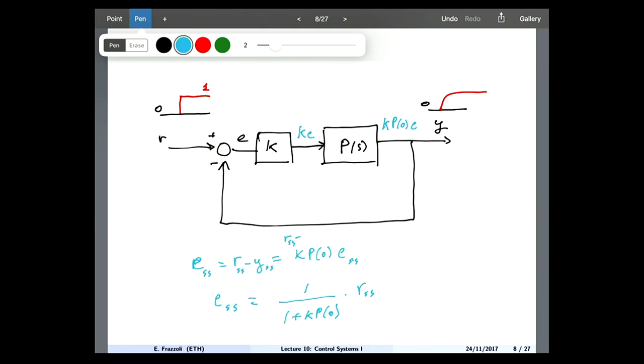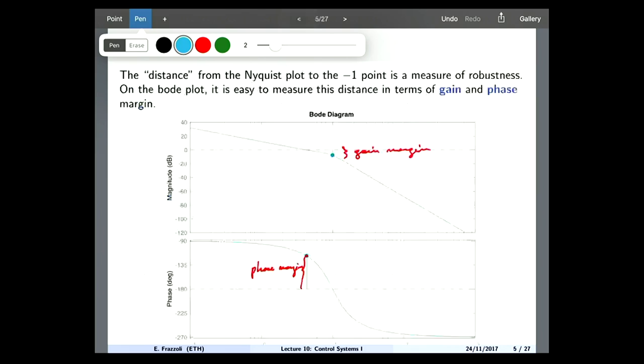So typically what happens is that by making the control gain large, you make the error smaller and smaller. You will never make it 0 just by this construction. Also notice that there may be the temptation, so I want the error to be very small, so I make K very large, but what may happen? Look at this figure here. What if I make my K very large?